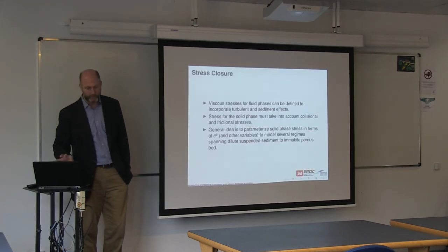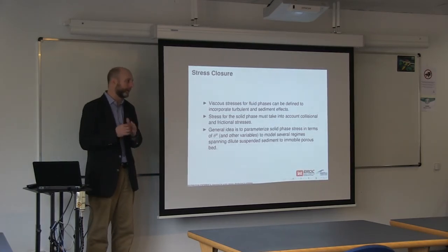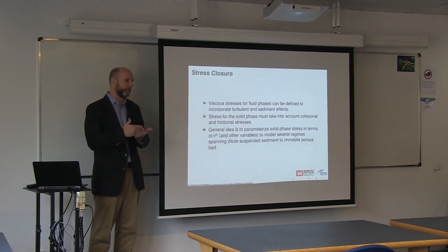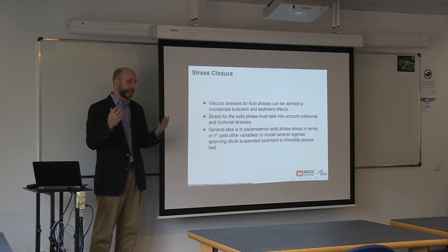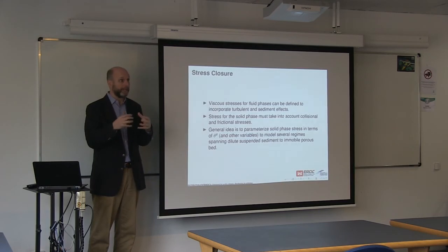So again, I skipped over the math here on the stress closure, but this model that we're looking at does have mechanisms in it that drive the velocities to zero as you approach a critical volume fraction. And so formally, I doubt anybody's ever proved that there's a discrete maximum principle in there, but there is a mechanism to prevent, basically as you approach the critical volume fraction, the solid phase is becoming a solid.